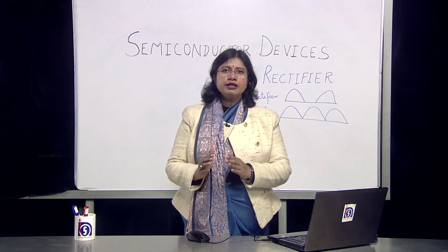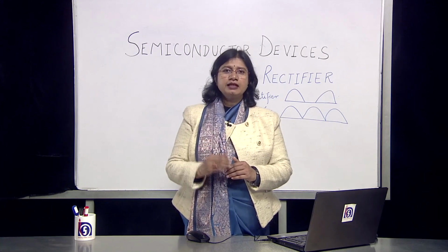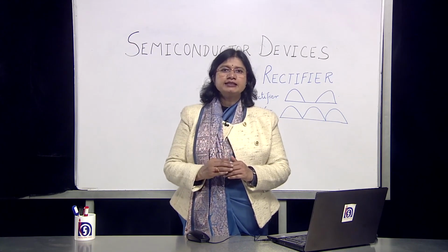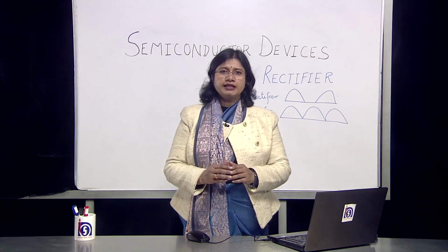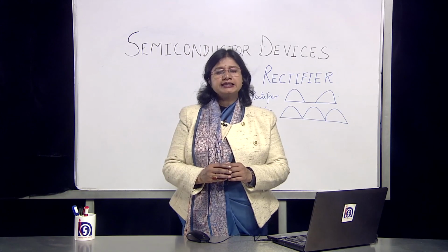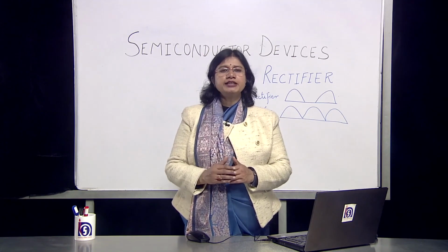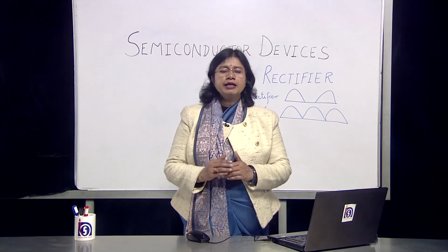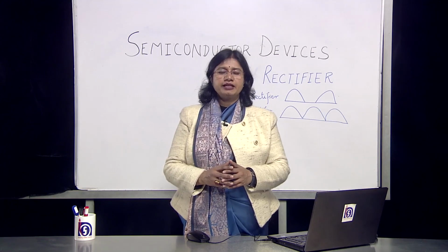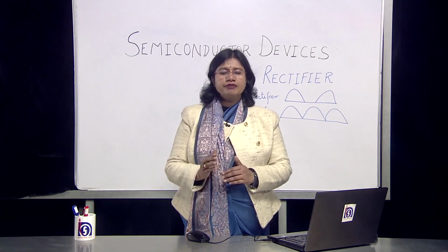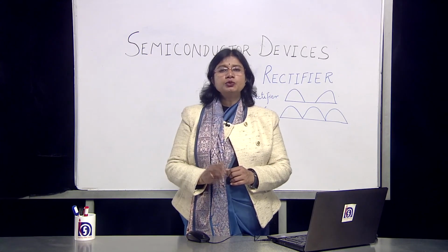We understood the working of a full wave rectifier, and in order to make our output less in terms of ripples, we understood the working of a filter circuit, which is a simple LC circuit, a combination of capacitors and inductors along with the resistance, which helps us in minimizing the rippling effect. These kind of rectifiers are commonly used wherever we require conversion from AC signal to the DC signal.